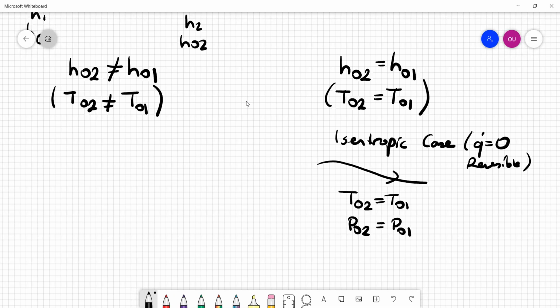If total pressure is changing, the loss in aerodynamics is due to viscous losses, due to boundary layers, the details of which we're going to learn this semester. But if we are ignoring these fundamental friction-related effects, then nothing can change stagnation pressure.